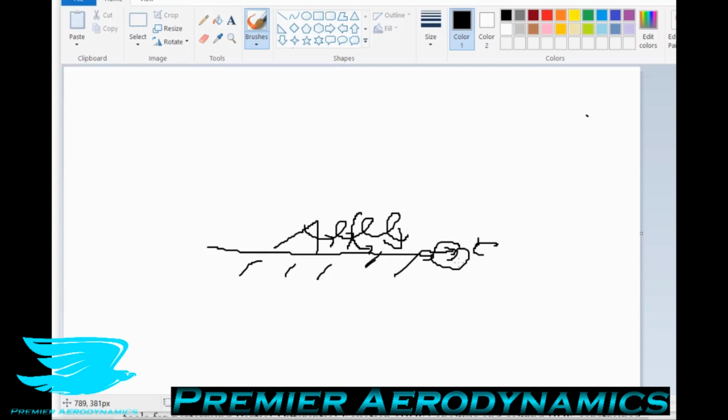And the reason why we put them just ahead of where the adverse pressure gradient starts is because that's when we start to get this deceleration. We don't really want to put it any further upstream from that, because there's not really much of a benefit to it. But any further downstream, then the adverse pressure gradient is already starting to affect the boundary layer there. So we've kind of missed out a little bit of the part that we really want to alleviate.